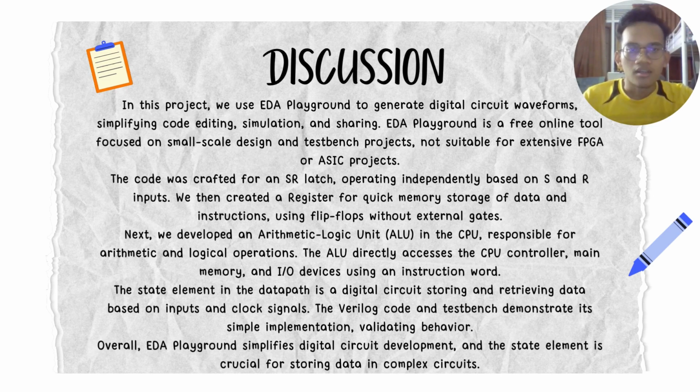This is our discussion. In this project, we use EDA Playground to generate digital circuit forms to simplify code editing, simulation, and sharing. EDA Playground is a free online tool that focuses on small scale design and test bench projects, not suitable for extensive FPGA or ASIC projects. This code was crafted for an SR latch operating independently based on S and R inputs. We then created a register for quick memory storage of data and instructions using flip-flops with gates.